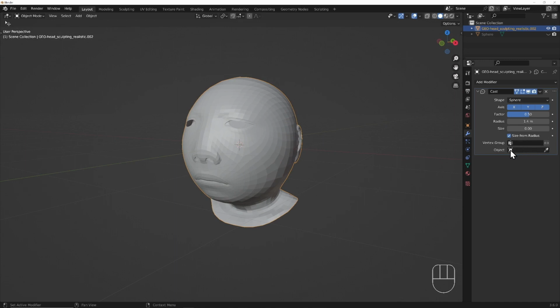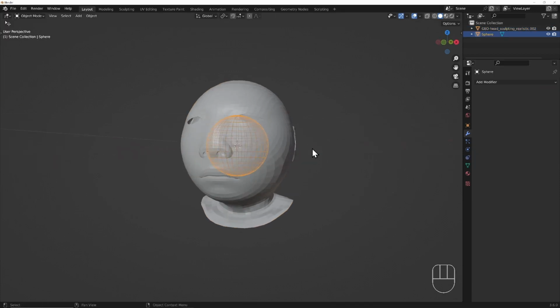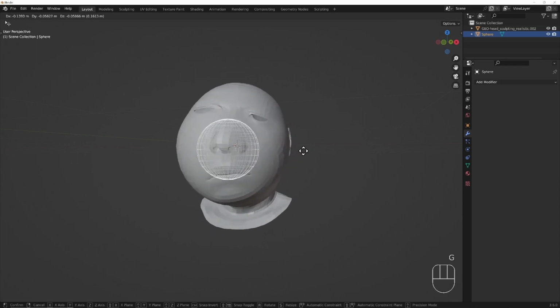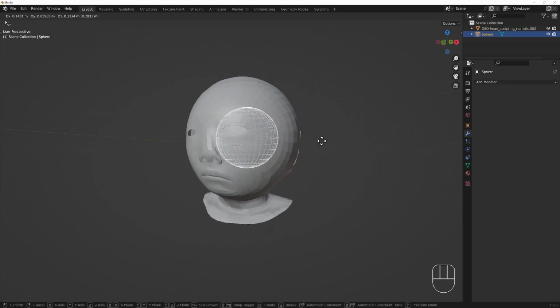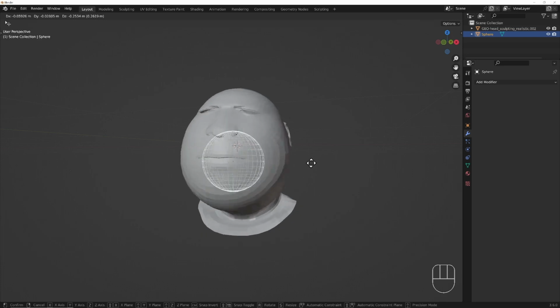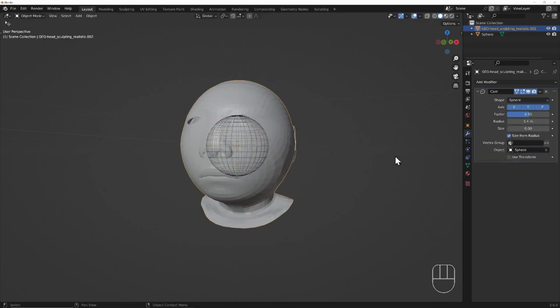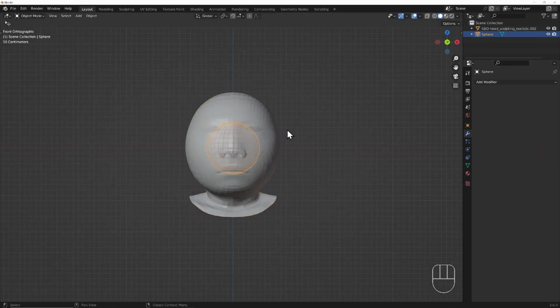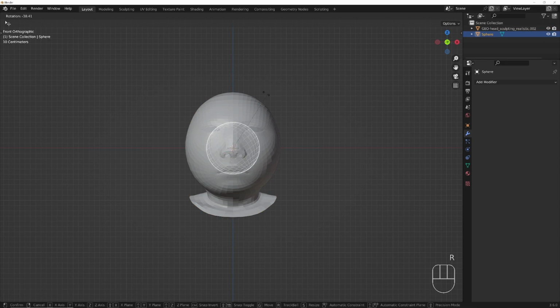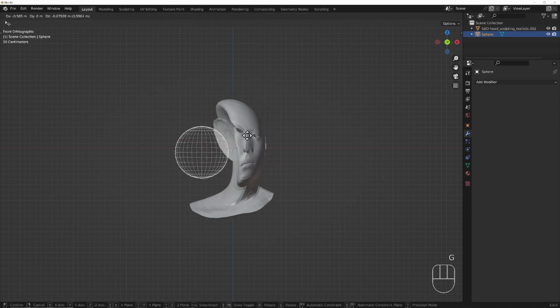Finally, you can use an object to adjust the center from which the shape is cast. I'll select the sphere which I used to demonstrate the boundary earlier, and moving that around, you can achieve the inverse of having to move the object's own vertices in relation to its point of origin. Note the Use Transform option. If this is disabled, the rotation and scale is ignored and only the object's position affects the cast.